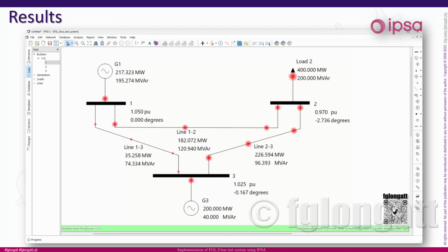So the dot, or the small red point that is moving on the transmission line, is even bigger. But when those two power flows arrive at the bus bar number 2, you must remember we apply the power balance equation. All the active power arriving at the bus bar number 2 must be equal to the power that is leaving the bus bar number 2.